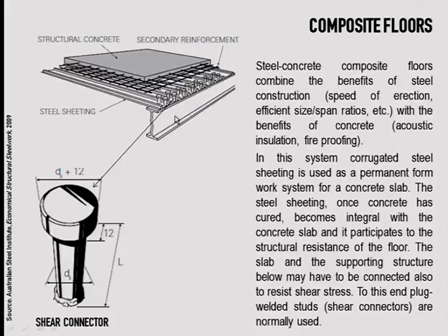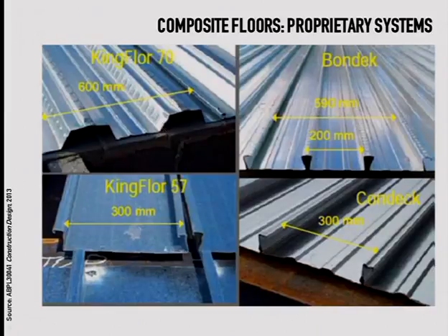And if we want to transfer shear forces between beam and slab, we use these shear connectors that, again, clamp the Bondek system to the beam. Well, Bondek is broadly used to identify the construction technique, but it is a trade name. So it refers to a specific brand. There are several similar systems, and generally we all refer to Bondek, but also Condek, Kingflor. They're all the same construction technique, just different trade names, all right? So just bear these in mind, just showing you a few examples.